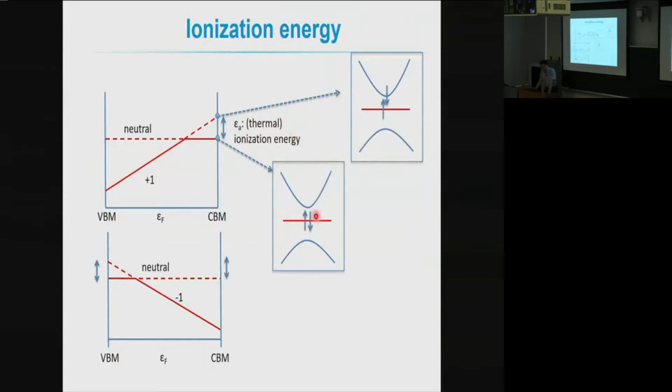So this is the energy that you need to excite or activate your dopant. In order to be a shallow impurity, which creates carriers, this energy should be around the thermal energy at room temperature, like 0.02 or 0.03 electron volt, or less than 0.1 electron volt. So this energy reflects the ionization energy of the defect, and in the case of the hole-like state, this is the energy to activate this acceptor. This is the donor.